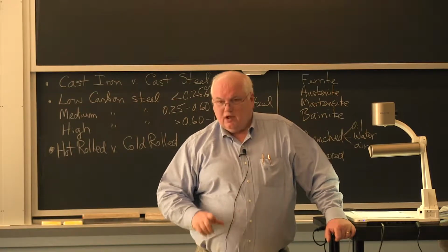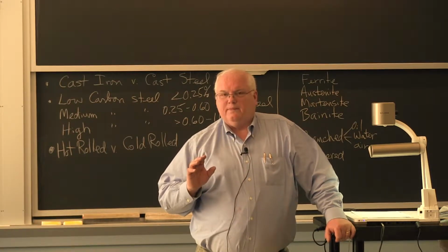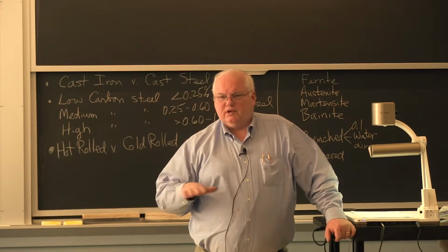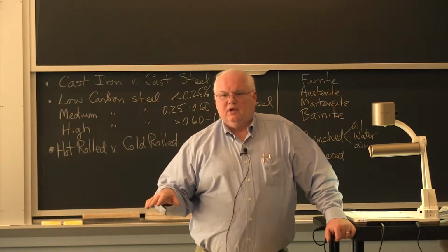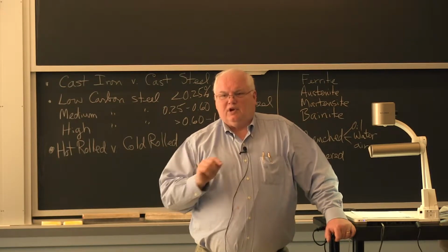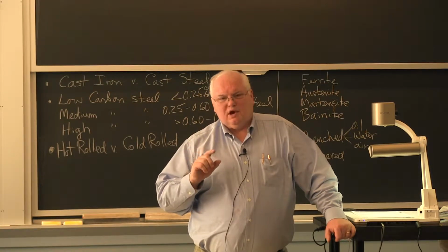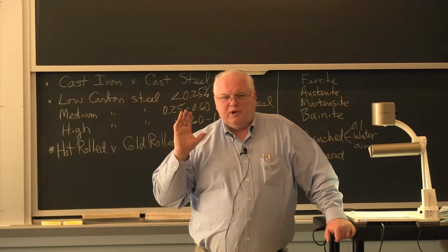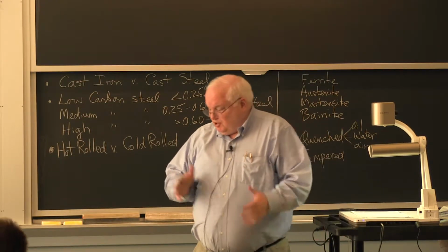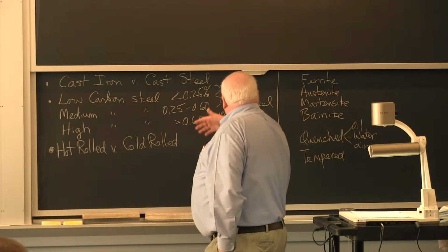No, you don't get any case hardening. I'll talk about case in a little bit. Actually, cold rolling should give you a nice uniform through-the-thickness hardness, in general. But you can do other things to get local hardness, surface hardening, and I'm going to talk about that. But you've got to remember, I told you, we know more about steel than any other material in the world, including silicon, okay? That's because it's a huge industry and it's had a lot of people working on it. So that's some of the terminology.